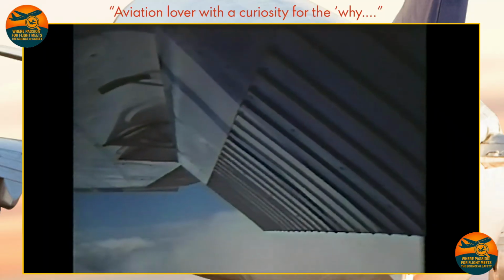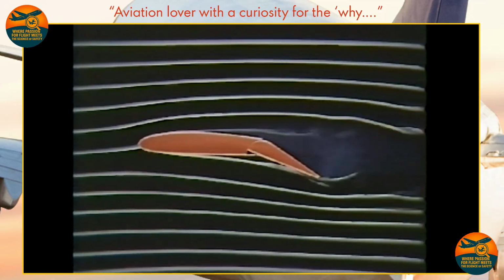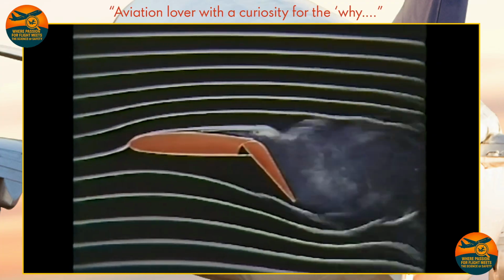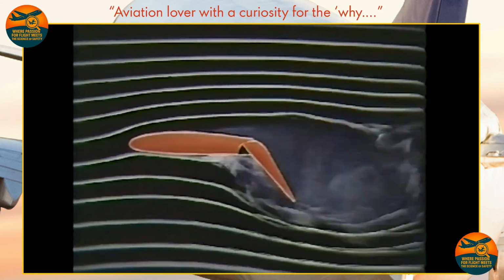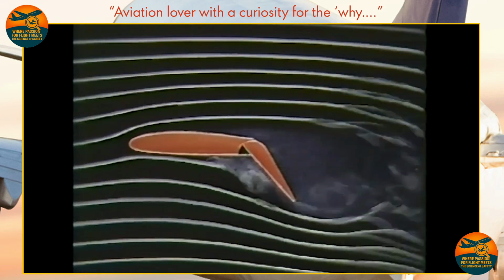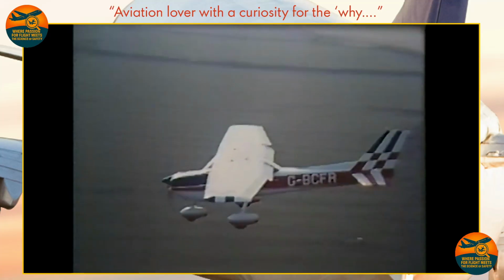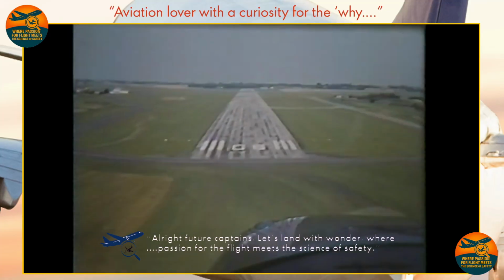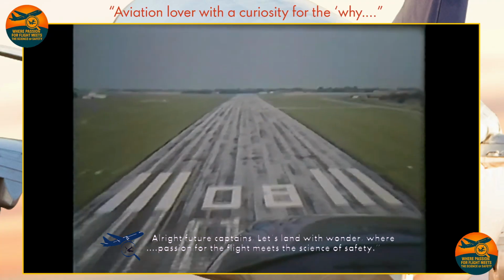With the flap fully deployed, lift is still maintained over the wing itself, but behind the flap, the airflow breaks up, slowing the aeroplane down by increasing another force acting on it, the force of drag. This enables us to approach the field at a steeper angle than we otherwise could, which gives the pilot a better view of the landing area, as well as a lower landing speed.